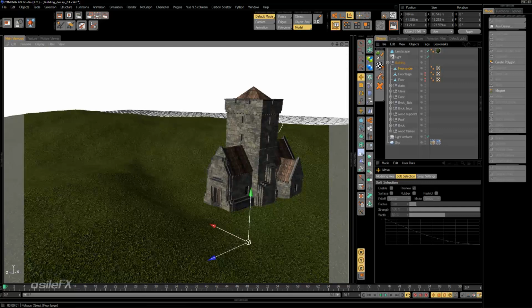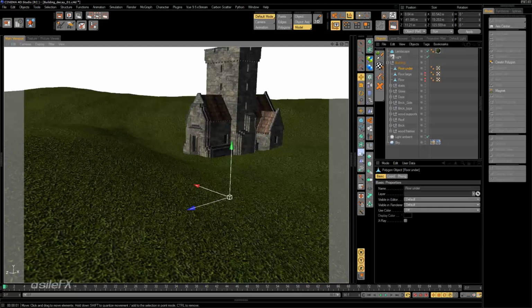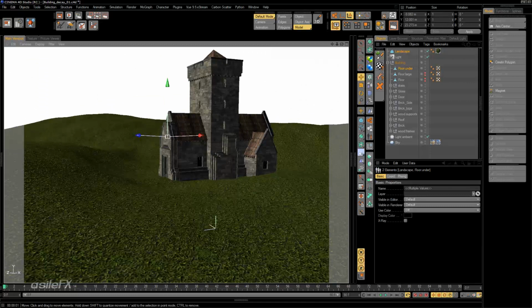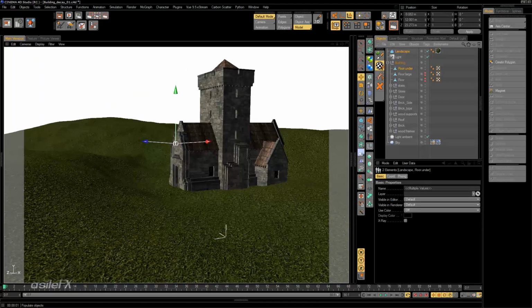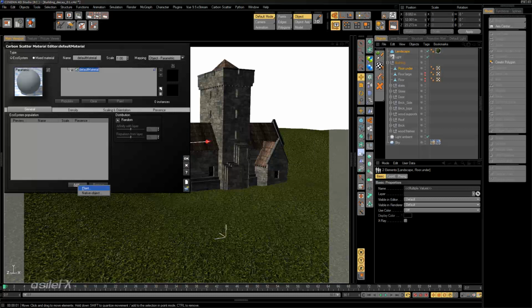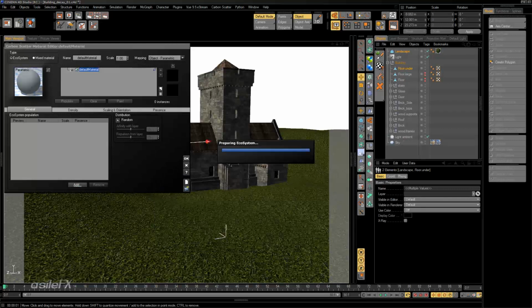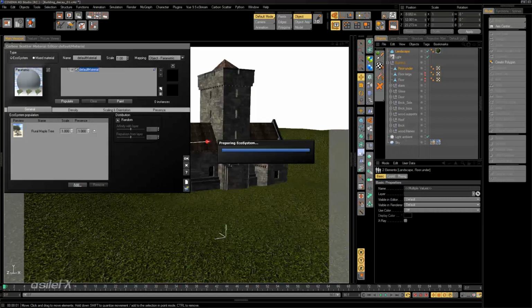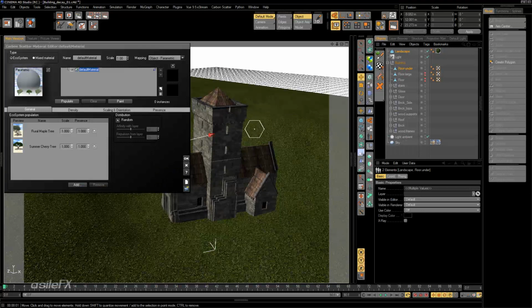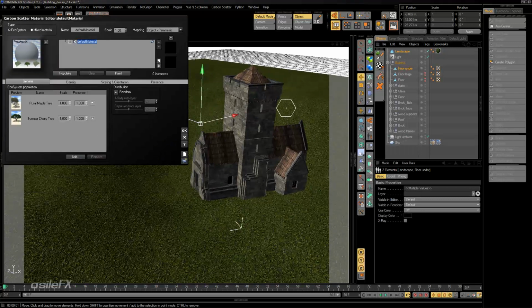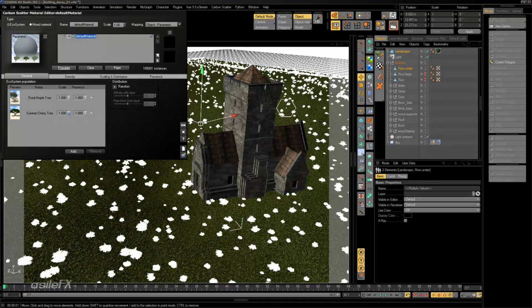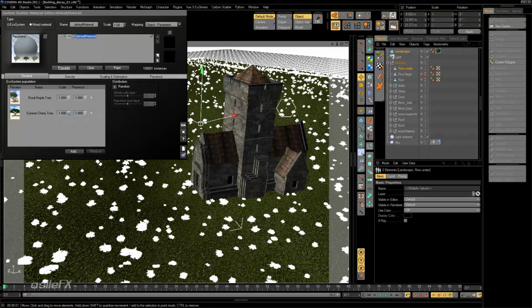So now if we select the floor under what we just made with that nice taper and select the landscape, we can go into Populate Objects, add in a couple of objects, and we'll just use cherry trees and maple trees. And what we're going to do is control either the density or, and actually I do need to change my scale.